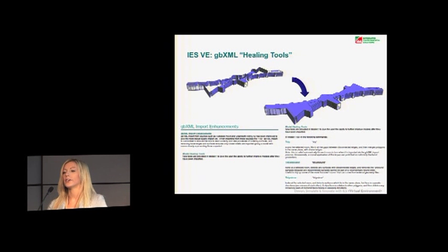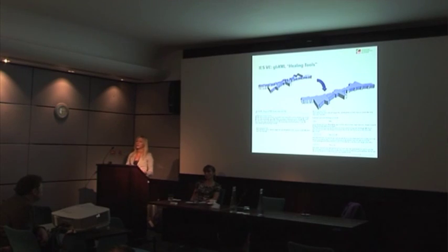Does that really matter to an early stage energy analysis, or even to your full energy analysis in the end? You don't want to consider that. It's making the calculation take too long, and it's insignificant information for what you're working on. However, if you're doing a daylighting view and you say, I really want to see these in this one room, that's when you're going to choose to import it using that level of complexity.